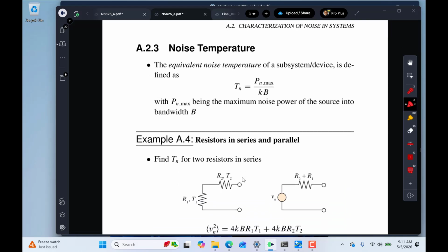So now I'll move into another way of characterizing a system. We can use the math that we've been going through, and we can come up with the equivalent noise temperature when we have something that has a non-unity noise figure. In other words, it will be hotter in an electronic sense than 290 degrees Kelvin.